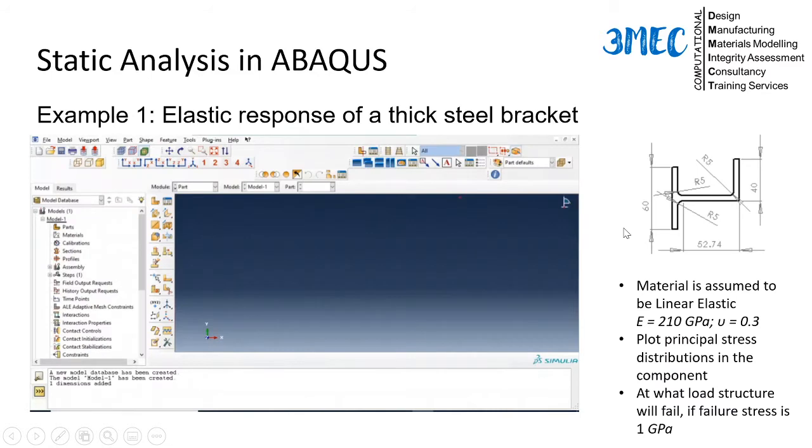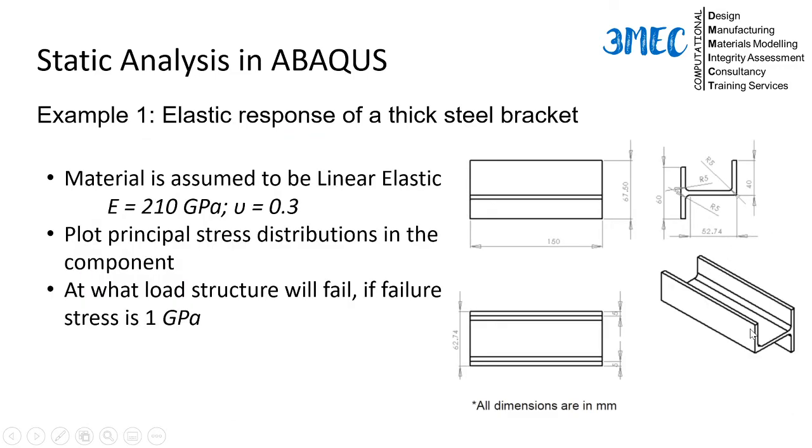Another important thing: in many cases you might not need a 3D analysis. Again, go back to my lectures and quizzes where I have discussed those concepts on plane strain and plane stress. To reduce the computational time and to make the right assumptions, we have a symmetry in the loading along the thickness direction, and we can also see that the strains in the thickness direction due to this loading will be approximately 0.